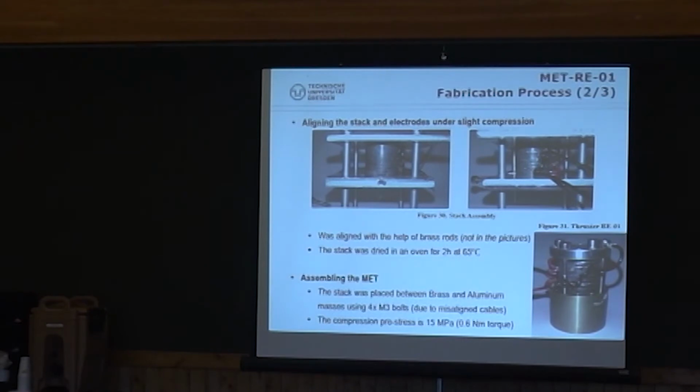We aligned the stack under slight compression, and then dried the stack at 65 degrees to make sure that the epoxy sets. And yeah, we ran into some problems due to pulling of the mechanical cables, and so we had to use fewer bolts than what Professor Woodward is using, decreasing the stiffness.